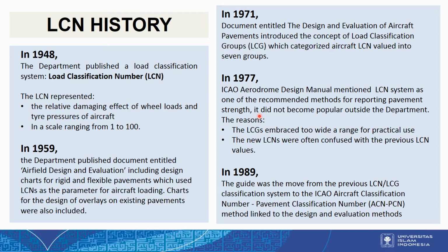Why? The reason the LCN system is not popular outside the UK is because the LCGs, or the load classification groups, which categorize aircraft LCN values into 7 groups, embrace too wide a range for practical use. And also because there were new LCNs, and the new LCNs were often confused with the previous LCN values. So this is why the LCN method did not become popular outside the UK.